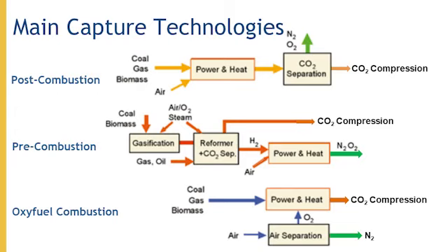So when we think about carbon capture, there are a range of technologies. The main three are listed here. If we're looking at the first process, this is the post-combustion process. You could think of it being applied to the end of power production. So you mix your fuel with air, you burn it, and then CO2 is produced along with other gases, and then that is separated and compressed.